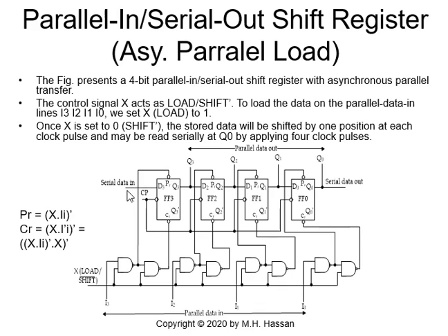This register also allows you to have a serial data in. So you can have a parallel data in, a serial data in, a parallel data out, and a serial data out in one register. And this is, of course, a shift register which will shift the data from the left to the right, because I'm taking the Q's to the D's here. Do you see? Okay. So very simple, it allows you to have parallel and serial data out, and we can have a serial in, serial out as well for this register, as well as parallel in, parallel out at the same time.